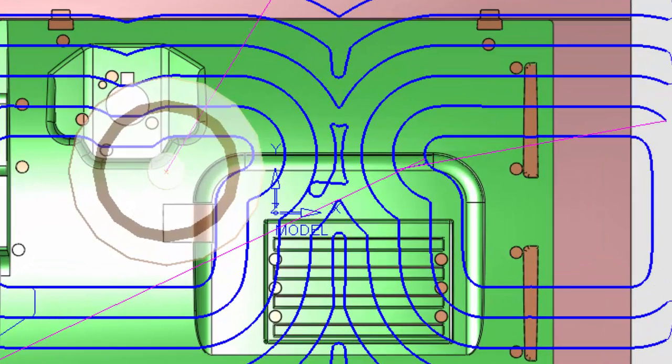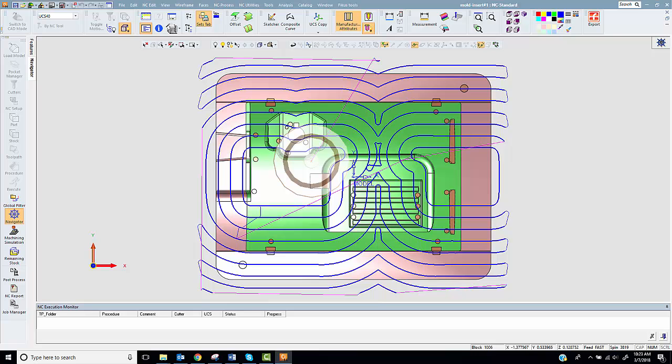I've stepped back and selected a 1/2-inch cutter and recalculated the procedure. At a glance, you'll notice stretch motions in a few areas. These are created with an option called Clean Between Passes. It allows the system to use a more aggressive step over while ensuring no nubs are left behind. You'll also notice all of the motions are rounded to prolong tool life. As you can see, this machining pattern is bidirectional. It does the final pass against the part as a climb milling motion.